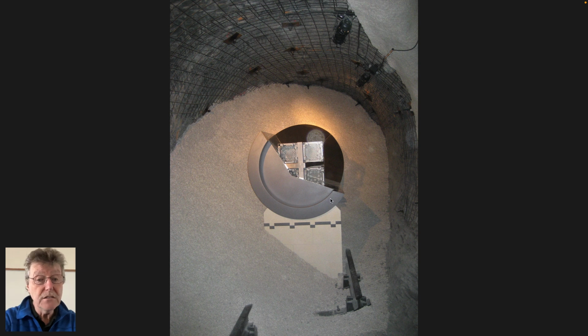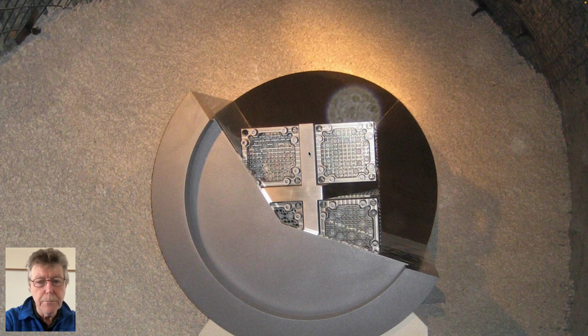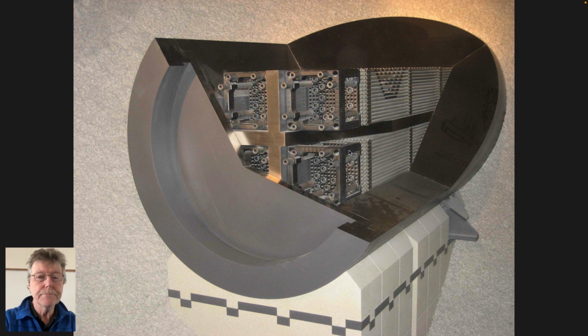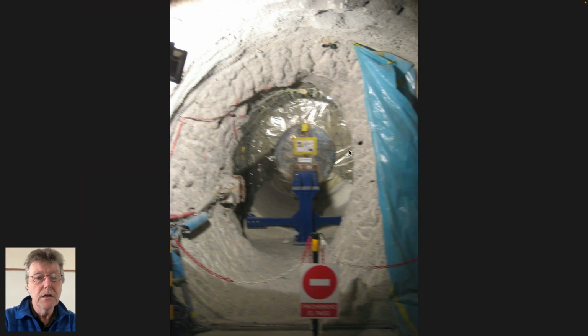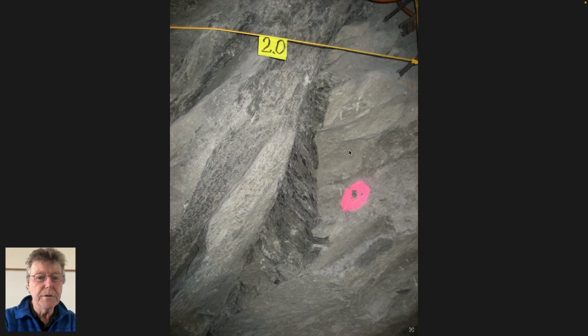This is one of those tests, actually. This is just a model representation. It is underground. This is what the waste containers would look like. So a bunch of radioactive rods in an assembly that are placed in a bentonite sheath. Now this is a container. This would be a metal container and then backfilled with bentonite around so that if this breaks open, you have low permeability, so not much water goes through here, and the radionuclides from this get absorbed in the bentonite. But this is a site where those experiments would be going on.